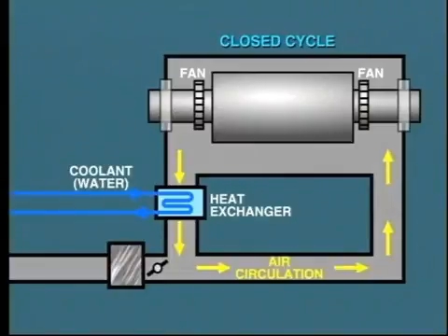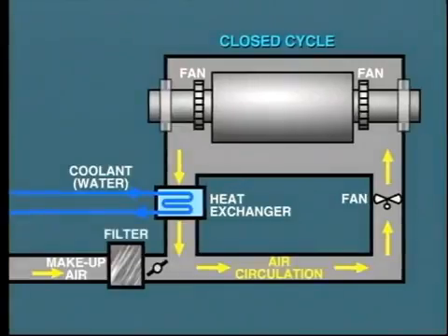Because of the additional pressure drop across the heat exchanger, it may be necessary in some generators to add a circulating air fan. Makeup air, to compensate for any leakage, is admitted into the suction of the circulating fan. Filters are provided on the makeup air inlet from atmosphere. In other designs, the shaft-driven fans are made larger to avoid the need for a separate air circulation fan. With this arrangement, makeup air is drawn in through the generator housing by these fans.